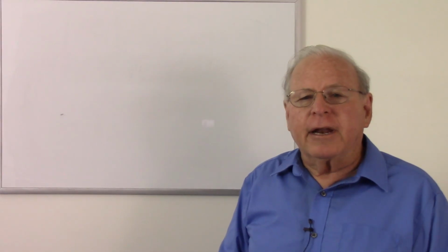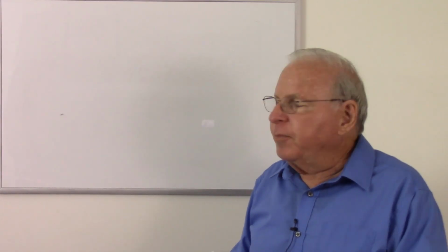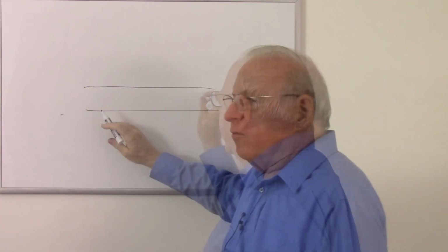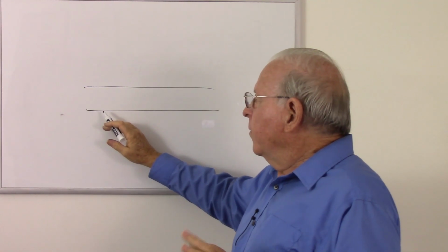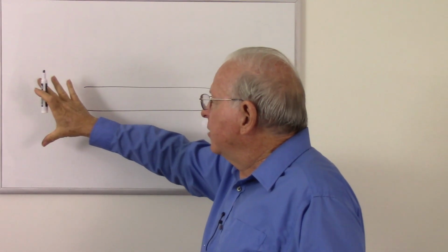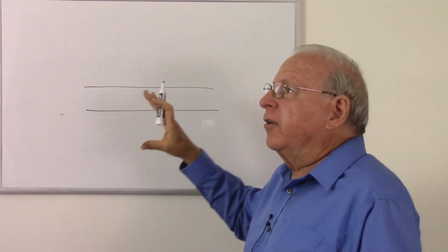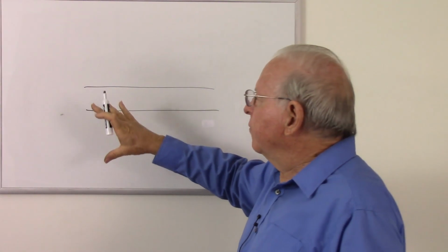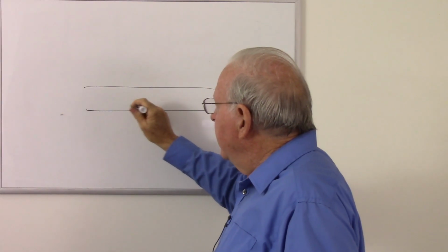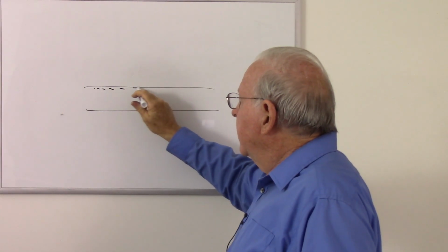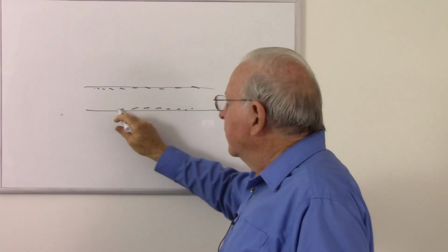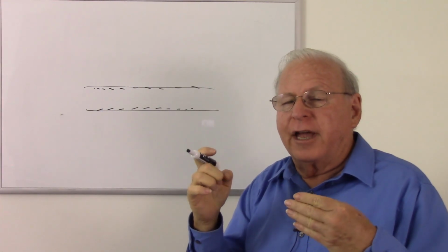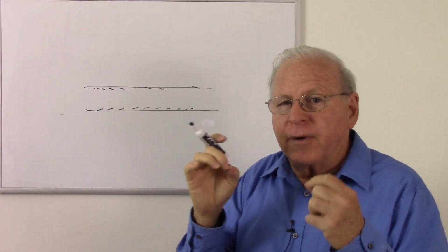But there's yet another way to mitigate it, which is a compromise between the two. So I'm going to start out with a chunk of glass. Let's make a glass tube of 1 index of refraction. But what I'm going to do is now put that in a chamber, and I'm going to put in some gases in there. I think they're germanium tetrafluoride and silicon tetrafluoride gases, and they're going to deposit a soot on the side. And then I'm going to heat it up and melt that soot, and it becomes pure germanium oxide and silicon oxide of the right proportion.